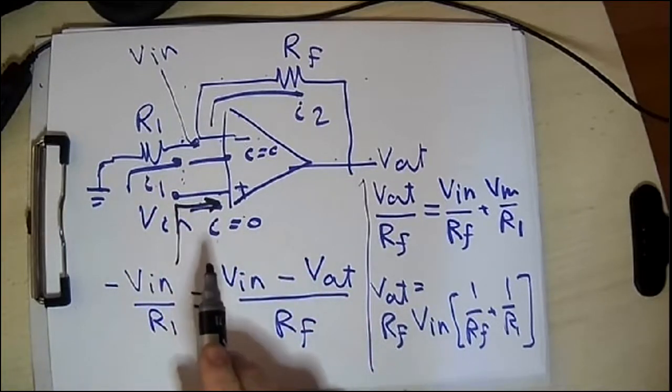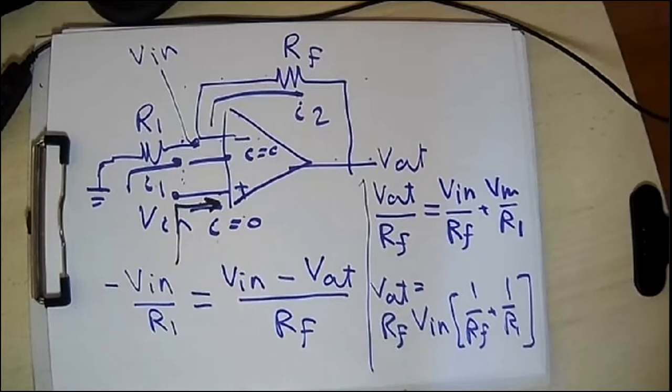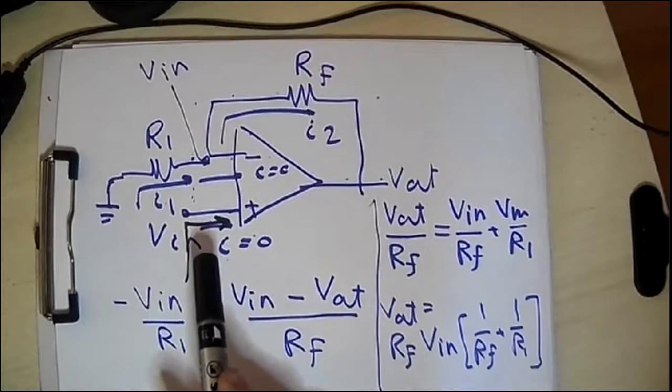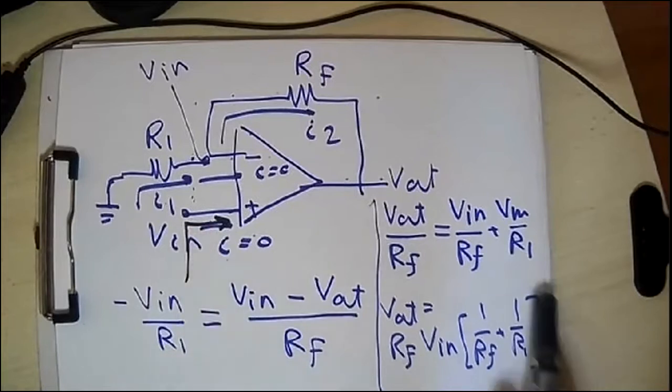So your input resistance in this configuration is typically infinity. That means that we overcome one of the main disadvantages of the previous configuration, where the input resistance was a function of the resistance R1, and whenever you increased it, you affected the gain. Now you have an ideal infinite input resistance without any effect on the gain.